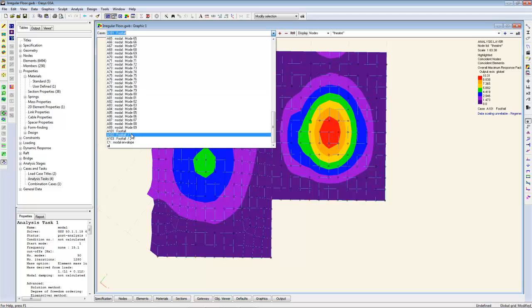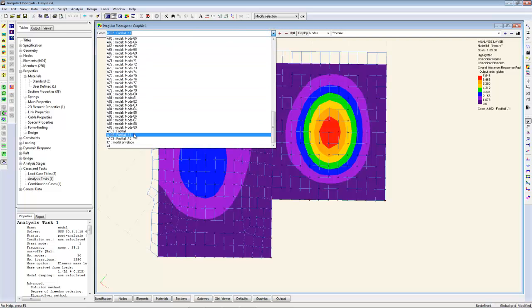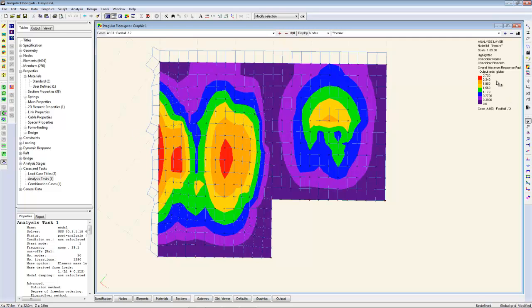If we look at the walking in that theatre with the reduced speed down to 1.8, the response comes down to 7.5. If we look at the response of the corridor on that theatre, the response comes down to about 2.7, which means, again, in this particular case, it's the people walking in the theatre which is governing rather than the corridor outside, but you do have that ability to see.